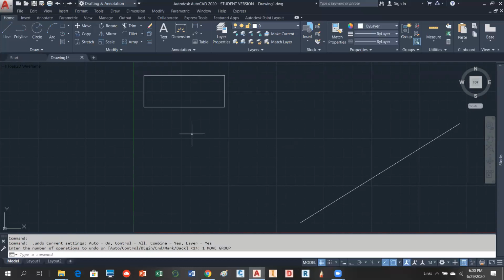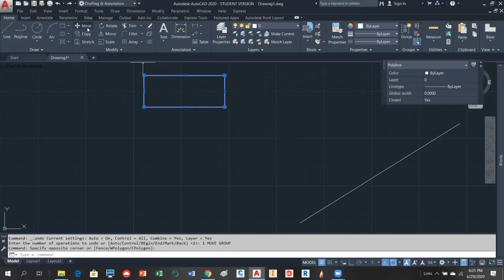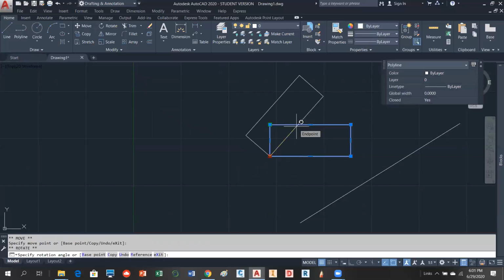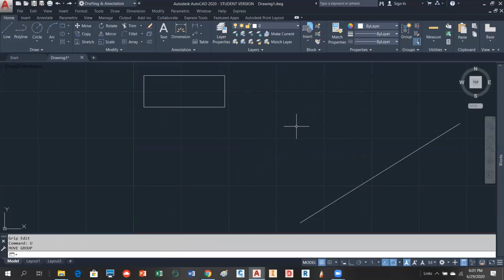So we have a command out there that is called the align command. When I move this thing, rotate it, and also scale it, that's what's called a transformation. When you just move an object, that's called a translate. When I do this, that's a rotate. And when I scale it, that's a scale. But the transformation command we're talking about here is going to do all three of those things for you in one shot, and it'll do it very precisely.